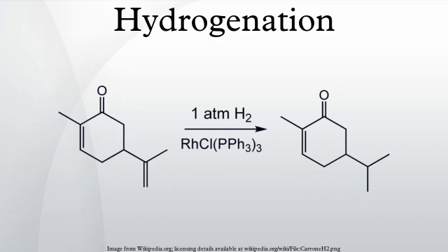In isomerization and catalytic reforming processes, some hydrogen pressure is maintained to hydrogenolyze coke formed on the catalyst and prevent its accumulation. Hydrogenation is a useful reaction for converting more oxidized oxygen and nitrogen compounds such as aldehydes, imines and nitriles into the corresponding saturated compounds, that is alcohols and amines.